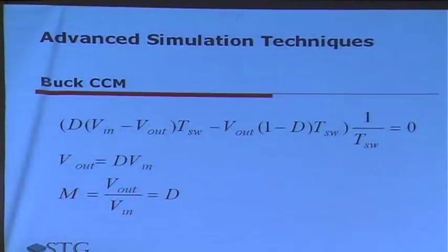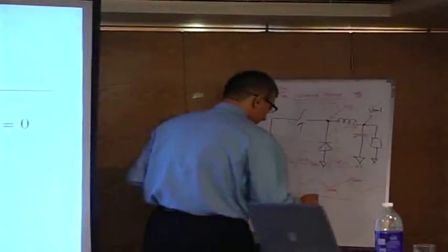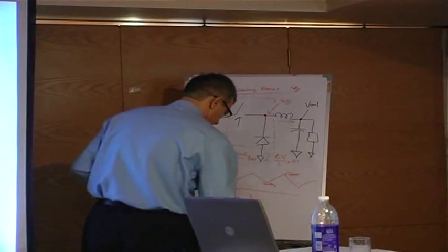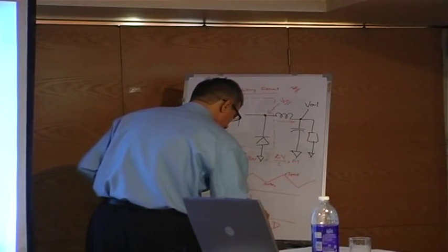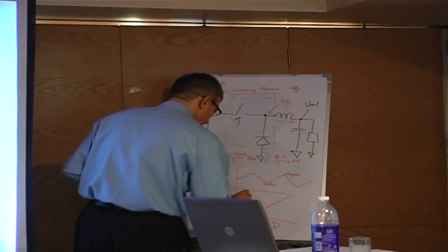So the buck converter has a linearity, okay? Linear control of the output voltage. That is a characteristic of the buck converter. It's a linear control of the output voltage, right? And I'm going to add a condition to it: as long as it is in a continuous conduction mode, it has got a linearity, so you can predict that if this is my D, I basically have a linear function which is V out by V in.